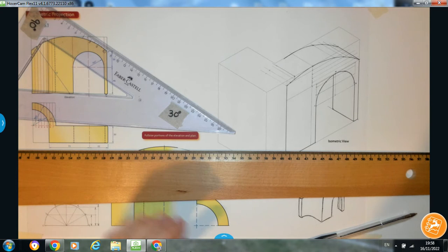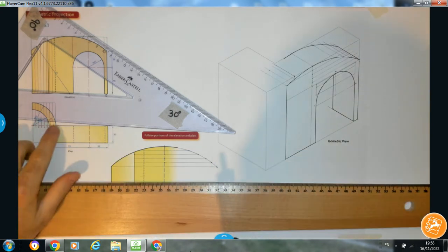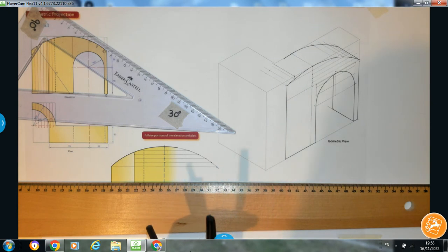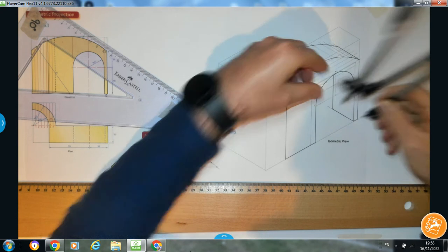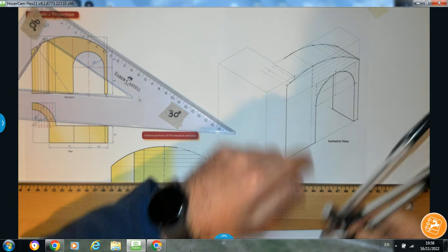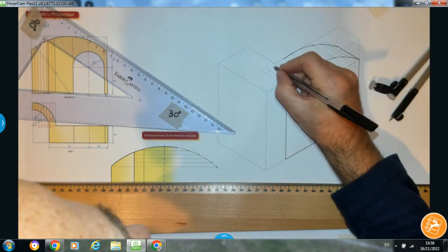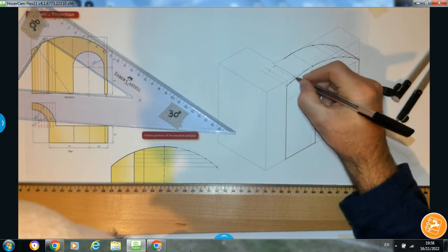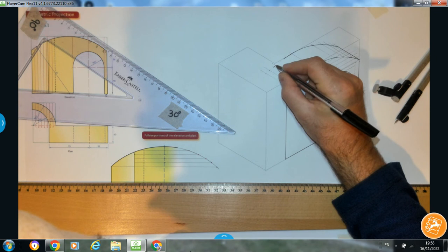And then from there, I take that 30 distance again, because it's still out 30 millimeters. So that 30 millimeters, grab it from here. Now come down to this point where it was on the curve. There we go. So that's telling me where it is, right there. I was doing it from the top, it actually should have been here, so I brought it down rather than bringing it out. So be careful of that.